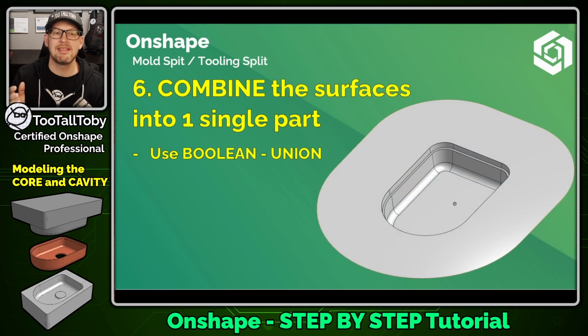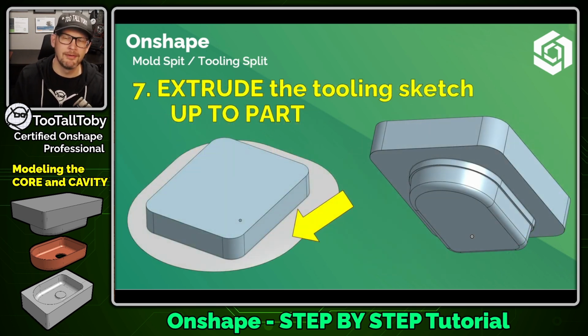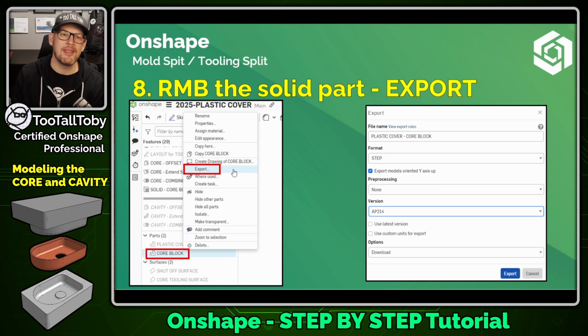Then you're probably going to have multiple surfaces that need to be knit together. So we're going to combine the surfaces into one single part using Boolean Union. That's how we do it in Onshape. And now you'll have that one single surface, so you can extrude the tooling sketch up to part, and you can select that surface as the end part for that extrusion. And that will leave you with a solid core block, so you can right mouse button on that core block and choose export. You can choose to export that to step, and then you can download the step file so you can share it with your machining team.